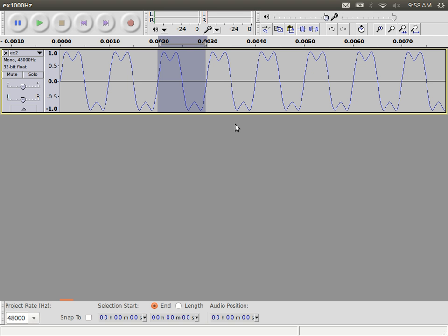When we design a signal to transmit, we need to consider these factors. The limitations will be, normally we have a fixed bandwidth to use. That is, you need to design a signal that fits within some bandwidth, and you want to get the highest data rate possible. In this case, if we use a bandwidth of 2 kilohertz, we get a data rate of 2000 bits per second, 2 kilobits per second.